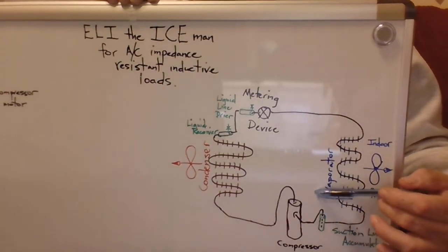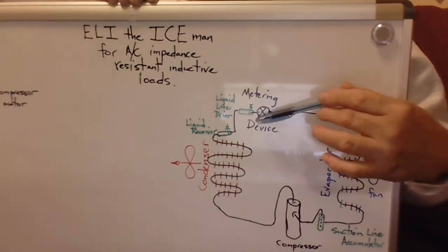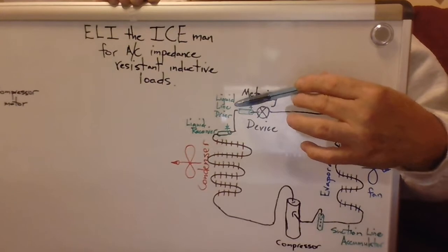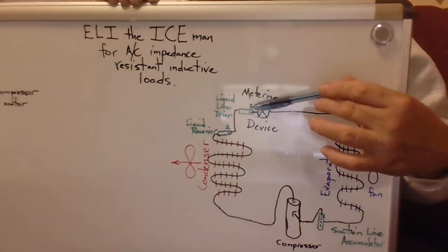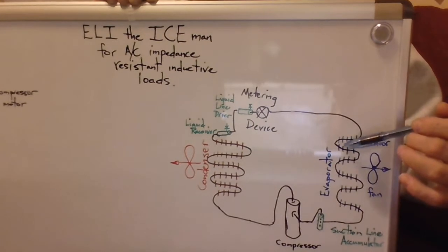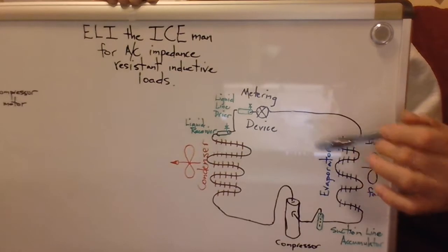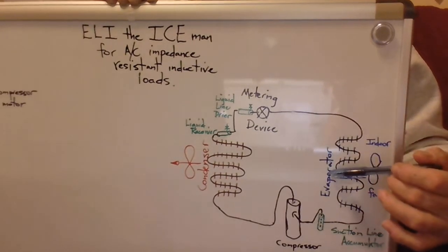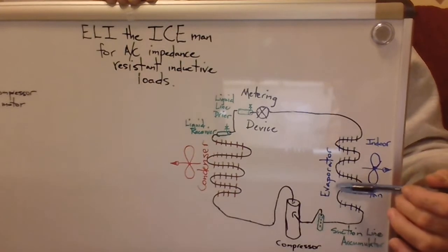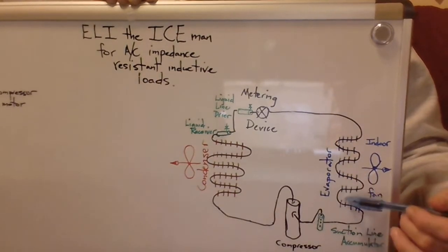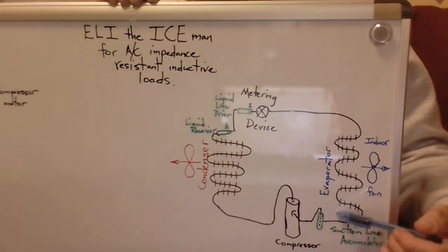that condition. And typically in that scenario, you can have a blockage in the dryer or the metering device or something to where you cannot pick up heat down here in the same way that you did previously with a fully functional dryer or metering device, but you're still picking up heat and you're putting it into the refrigeration, but there's a lot less of it, so the superheat rises and goes up quickly.